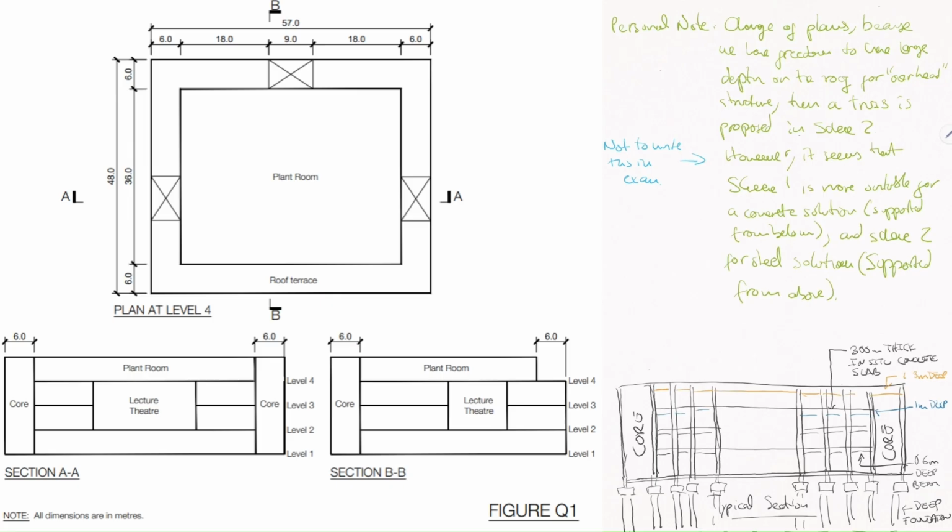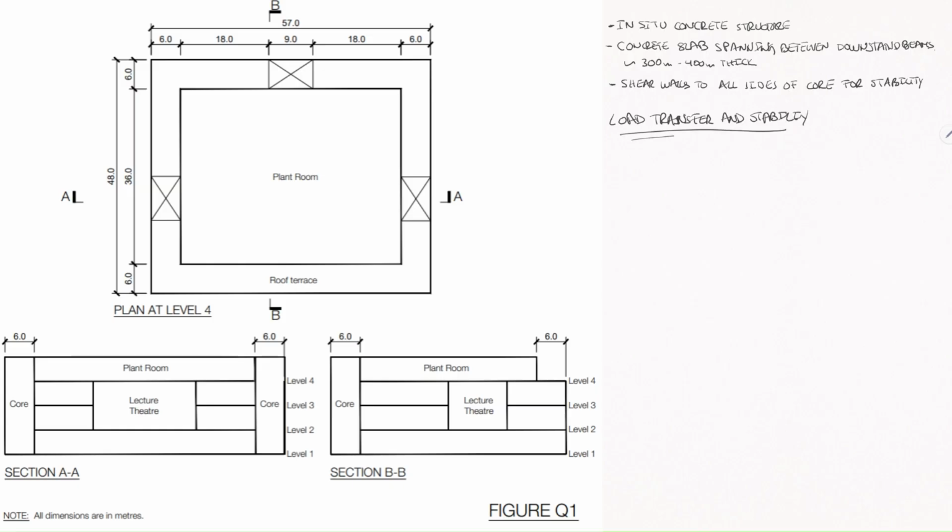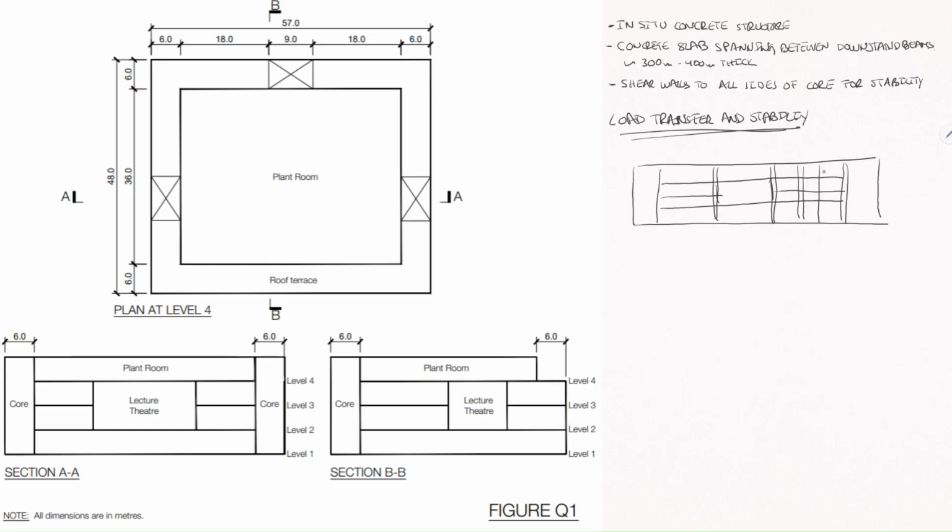What tends to happen, based on the previous exams, is that a lot of people give 2 quite similar schemes and only change the material and maybe a few column arrangements. But the moment that you change your load path, meaning that one option is supported all in gravity and the other maybe with some tension elements or some cantilever elements, that changes your scheme 1 or your scheme 2. It makes them very different. And that's, to me, the key: make sure that you have those 3 things different between scheme 1 and scheme 2. Different material, different column arrangement, and different load path.